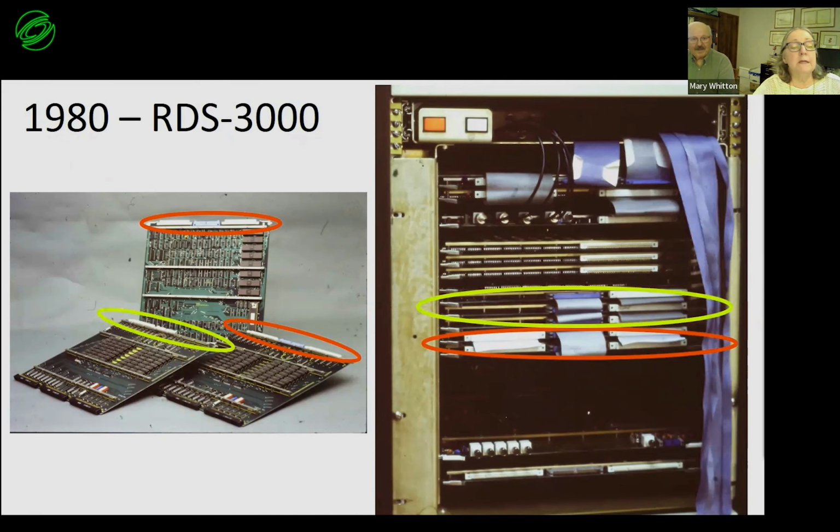The lower right is the microcode memory, and it has a direct interface to the processor board. You can see them not connected here and then connected. And then the one on the left is the static RAM for the data store. In this picture, those are frame buffer boards, and then the video output board. And one of those would be the frame buffer controller, and one of them will be look-up tables. You can't really tell from here.